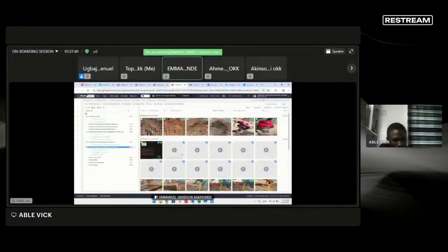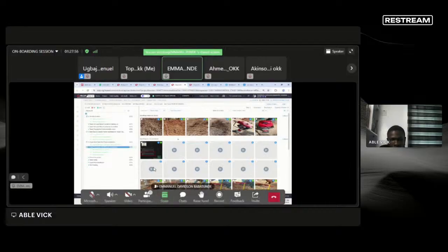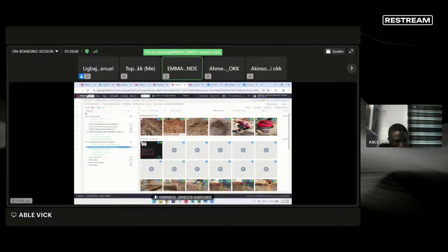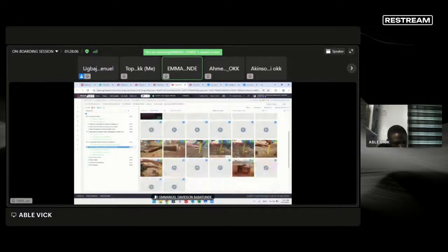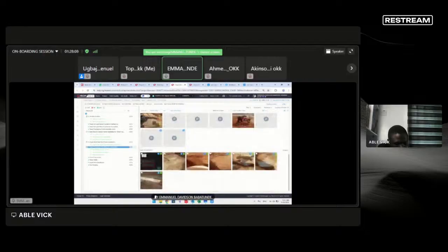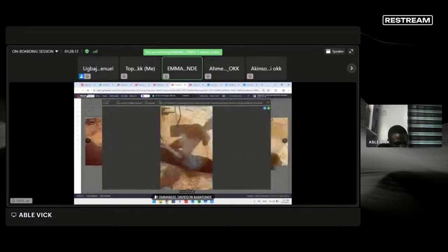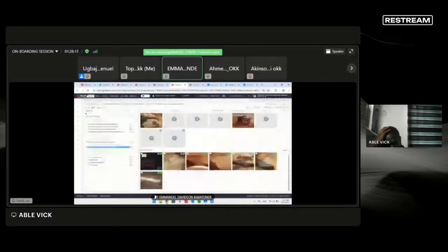And for guide wire compaction, we also maintain the 200 mm layer. You use manual compaction till maybe you get to 1.5 meter height, so the remaining 500 can be done with your compacting machine. You understand it? Because you are using manual compaction does not mean you will now stop the water process. Once you finish with manual compaction, you pour water in the trench, then continue the manual compaction again. You pour water just like this. See how this person is doing it: after compacting a layer, you fill it with water, then compact the next layer.